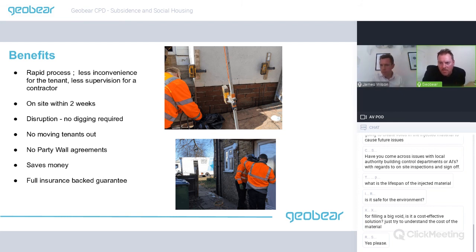So I think you missed Sherwin's. There's Sherwin's question there about how many floors this soil can be injected. So basically 5 floors is a rough guide, and it's a bit more scientific than that. We've got specific bearing capacities and strength that we can exert on our material. So roughly 5. So not high-rise. I wouldn't class it as high-rise. So that's probably another limitation as well.